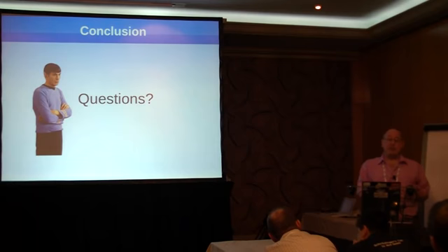SPI can be bit banged as well as I2C, but again, it needs more GPIOs, and you have to steal more GPIOs from other places. So yes, it can be used, but in my context, I want to try to keep everything as simple as possible and do as little damage to the board as possible when I'm trying to bring it up. You could bit bang I2C to a GPIO expander and then use that to bit bang SPI.